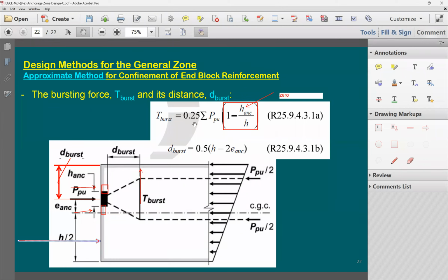So if I'm going to be buying an element from a factory, like a pre-stressed element, the amount of reinforcing needed there for the anchor is going to be very small compared to doing it at the site. If you like to do post-tension, what does it mean by post-tension? It means you cast the concrete first, and then after you cast it, you start to apply the pre-stressing.